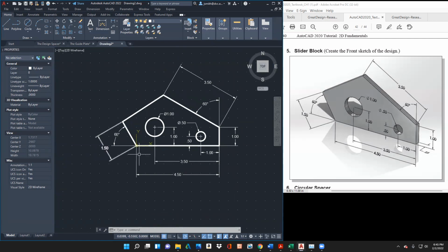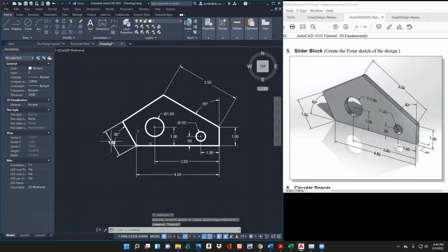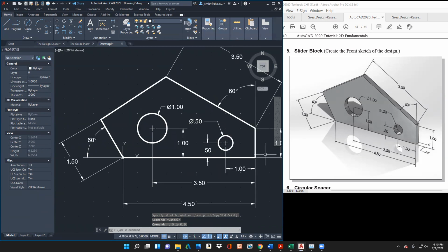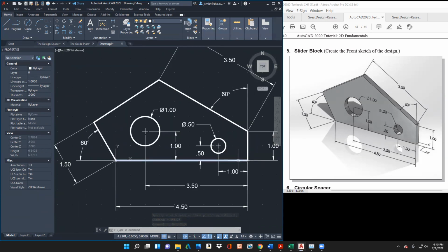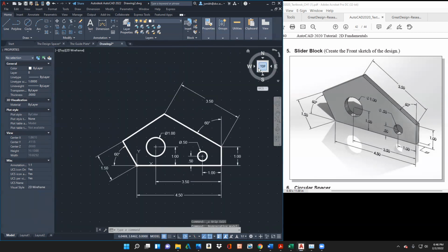Always avoid any text overlap though. For example, if this was on top, you want to avoid that kind of thing. So avoid any text overlap. Make sure that you have gaps from the part line. If you don't, it usually means that instead of selecting, you selected at the wrong place. So you just want to fix all that. I'm going to center all this.